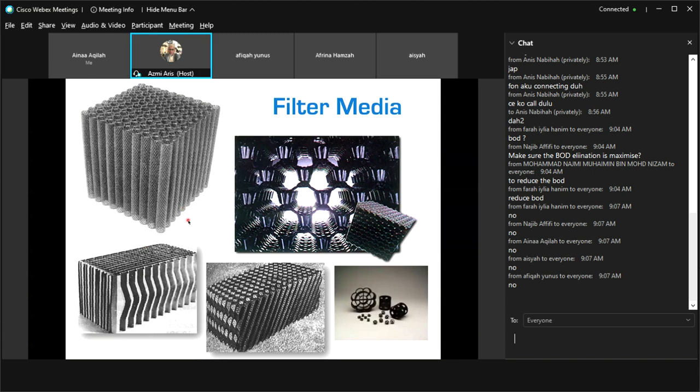They called it trickling filter. Trickling filter is actually a historical name established in the old times, but it was not changed until modern times. But we have to understand that in a trickling filter, there is no filtration process taking place. The removal is made by the microorganisms that form the biofilm on the surface of the media. That is actually what happens.